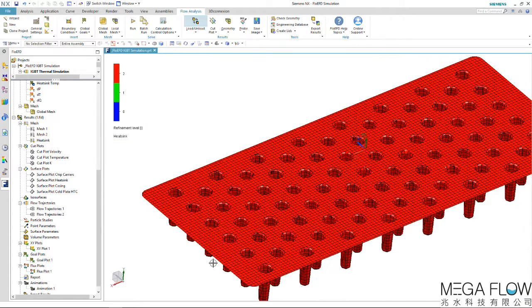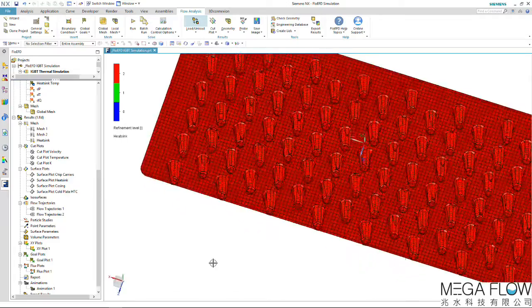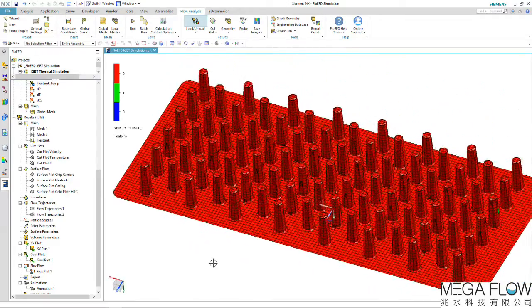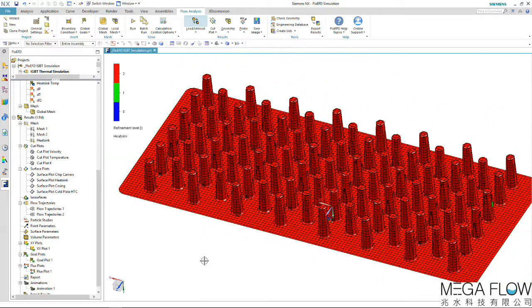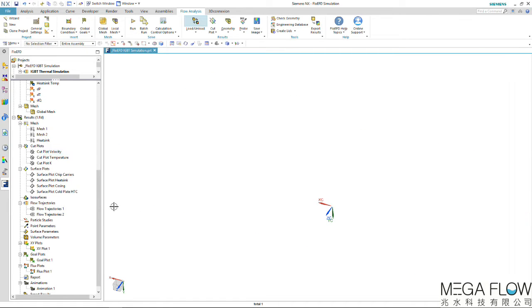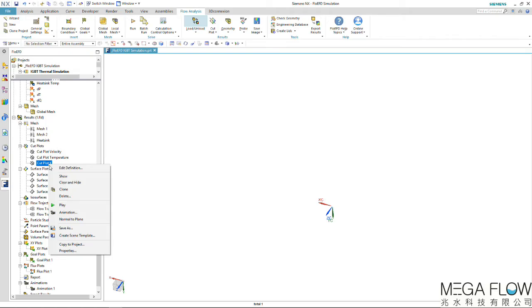If we plot the surface of the heatsink base with mesh, we can see the smart cells which touch the water region. Proprietary wall functions are used in the smart cells to apply the boundary layer. FloEFD uses the K-epsilon model for the bulk flow turbulence and an empirical engineering model for the near wall effects, which have been calibrated over a wide range of Reynolds numbers.